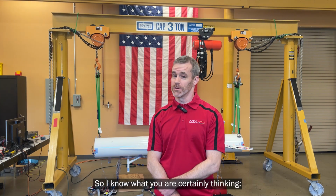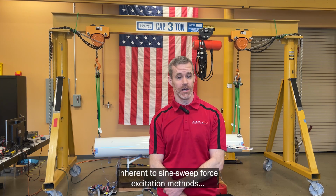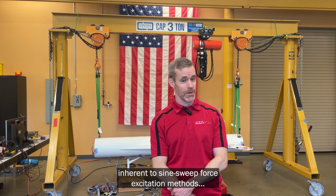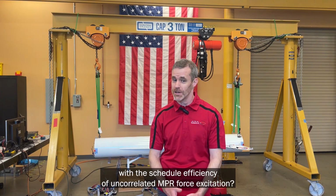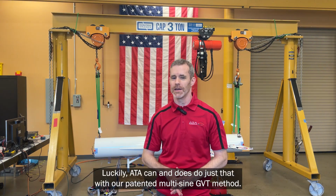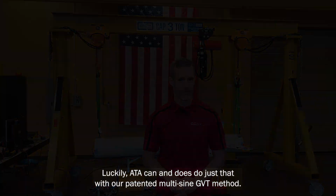So I know what you are certainly thinking. Wouldn't it be awesome if we could combine the excitation energy inherent to sine-sweep force excitation methods with the schedule efficiency of uncorrelated MPR force excitation? Luckily, ATA can and does do just that with our patented multi-sine GVT method.